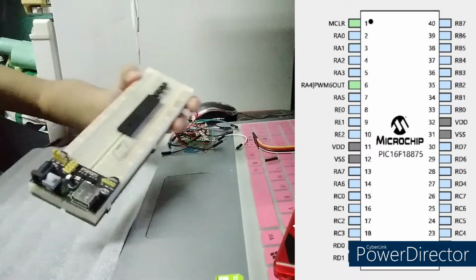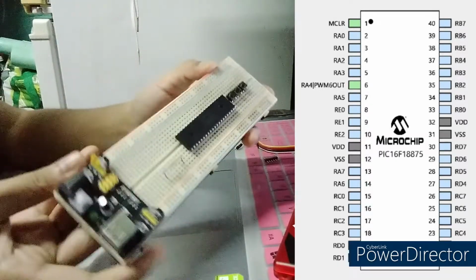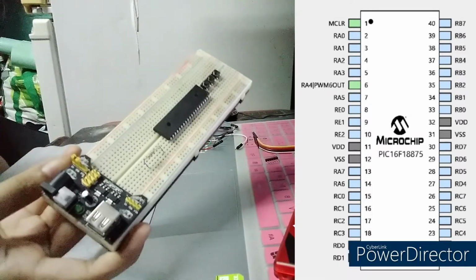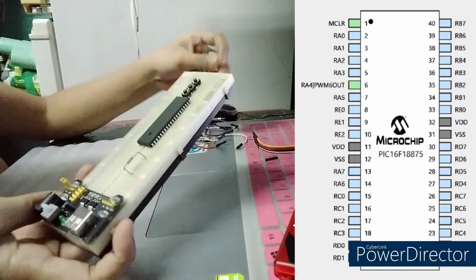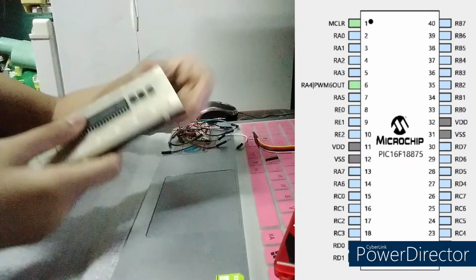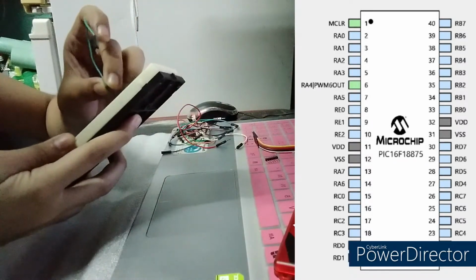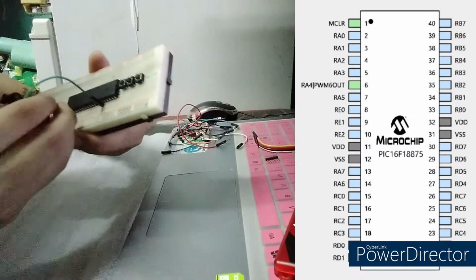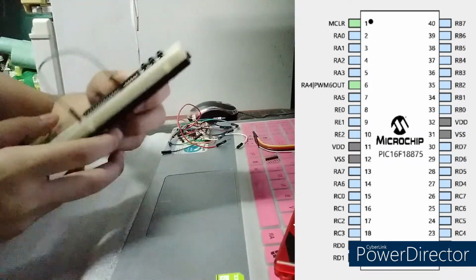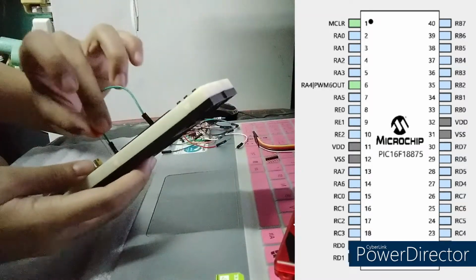In accordance with our pin configuration, we connected our LED as our output on RE4, or on the 6th pin of our IC. So let's first connect it. Let's count 1, 2, 3, 4, 5, 6. So this will be our output. Let's connect it here, and let's connect our LED here.